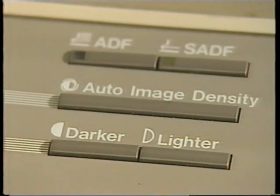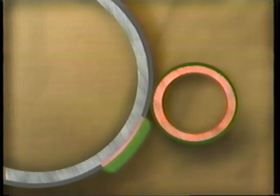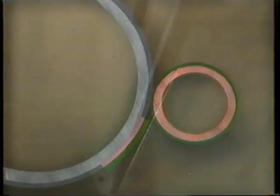To produce a lighter copy, the main board increases the bias voltage to hold back even more toner. This reduces the amount that's attracted to the latent image, resulting in a relatively thin deposit of toner on the drum. For a darker copy, the main board lowers the bias voltage, so very little toner is held back on the development roller. The result, a greater thickness of toner on the latent image and a darker copy.